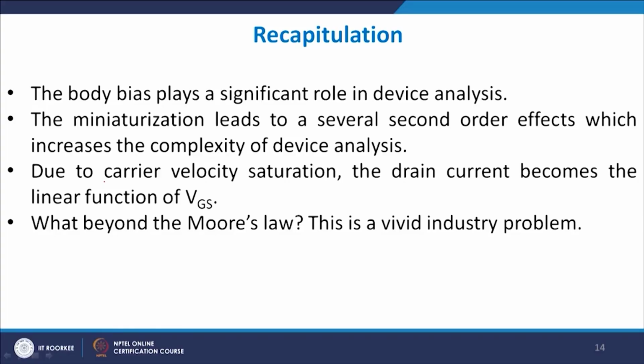The third point is that due to carrier velocity saturation, the drain current is almost a linear function of VGS, right. So it is VGS minus VTH whole square in the long channel case, but here it is a linear function of VGS, right.